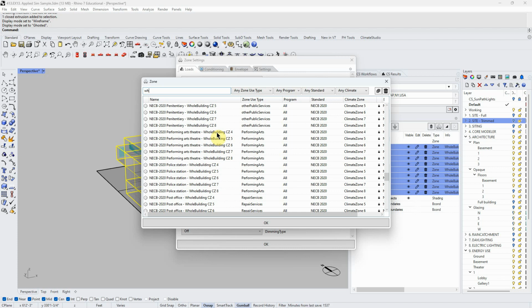What it does is it says, okay, we know there's a mechanical room, we know there's bathrooms, we know there's corridors, and that it's not all the same, so there are going to be different mechanical system settings and different occupancy, number of people in the different zones. We're just going to create one set of inputs, based on our knowledge and the survey that we've done, from DOE, probably, or a different organization. We're going to decide what those settings should be, and it'll be good enough for the entire building.